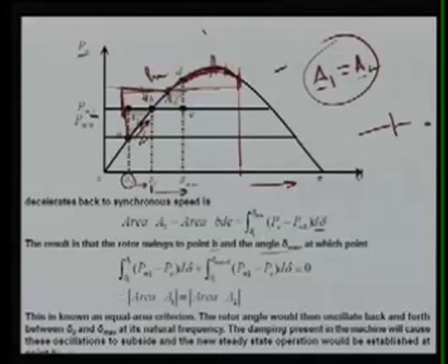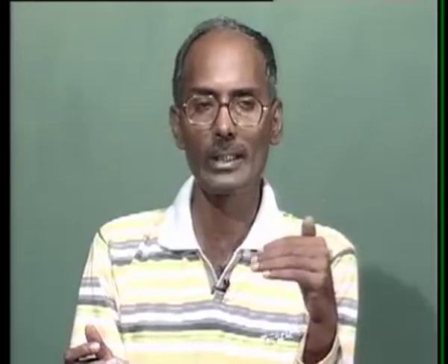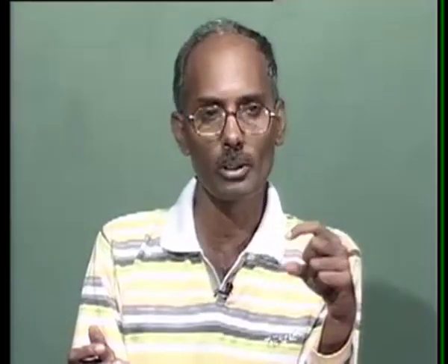And this classical approach, as I said, is limited to the single machine infinite bus or two machines, here this is one machine and here it is another machine. Then we can analyze, and using the equal area, here area 1 is the energy storage that is accelerating. So the energy that you are giving, that increase, is basically in terms of accelerating, and here is decelerating. So in this lecture I have taken only one case, when there is a sudden change in the input power.